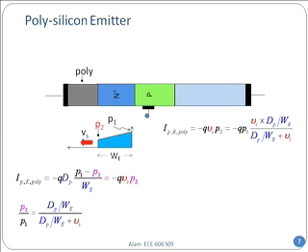Now, we can easily calculate, because I have P2, I can put it in that expression, minus Q V sub S multiplied by P2, and calculate the current. Do I know P1, by the way? What is P1? This is Ni squared divided by Ne, exponential of that voltage minus 1, right? That's the P1, the junction. So I already know P1. V sub S is a material property, and the diffusion coefficient and the emitter width, these are all known. So therefore, I could easily calculate this current.